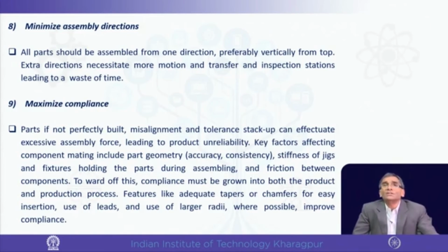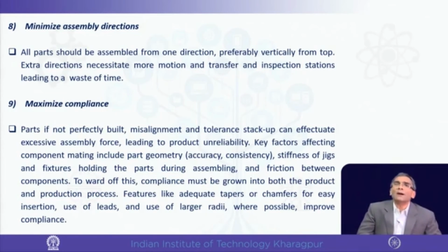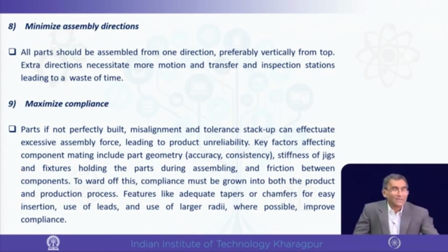Minimize assembly directions. It should not be done upside down, left, right; preferably it should be done vertically: something is kept, and on top everything is put in, and assembly is complete. Because the more upturning, downturning, etc. is happening, the more time is wasted and it does not help.